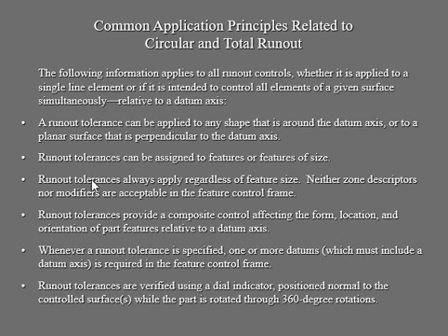When you deal with a runout, we are going to take care of all these things that were listed right here. As we go into the example, you will be able to see them. So right now, just read it, and you will be able to connect to it before you ever get into the example. Your runout tolerance can be applied to any shape around the datum axis. Since you're dealing with circular, you always have to have a center and an axis. That's what we're talking about here.